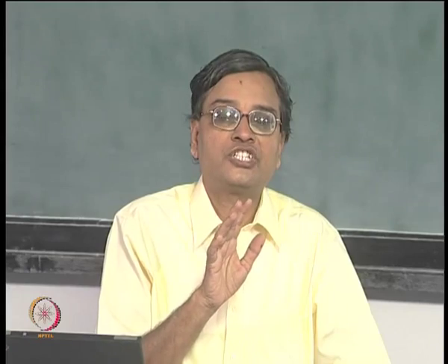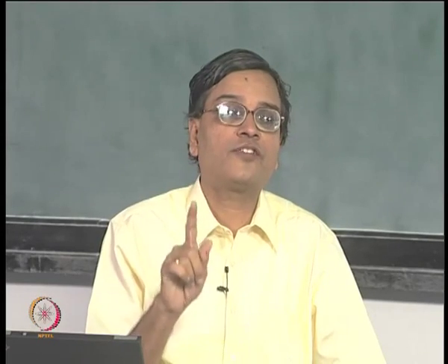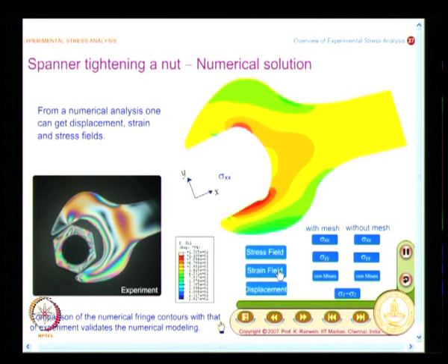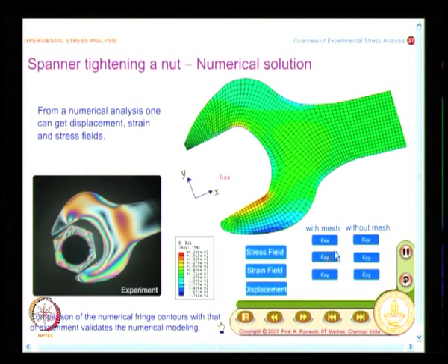The moment I come to numerical techniques, the greatest advantage is the shape of the geometry of the problem on hand does not pose any restriction, but you have to do a lot of computational effort, but you get whole field information. So, I can also get the strain field, and till now you have not seen strain field as a plot, and this is with mesh, and you can also see without mesh.